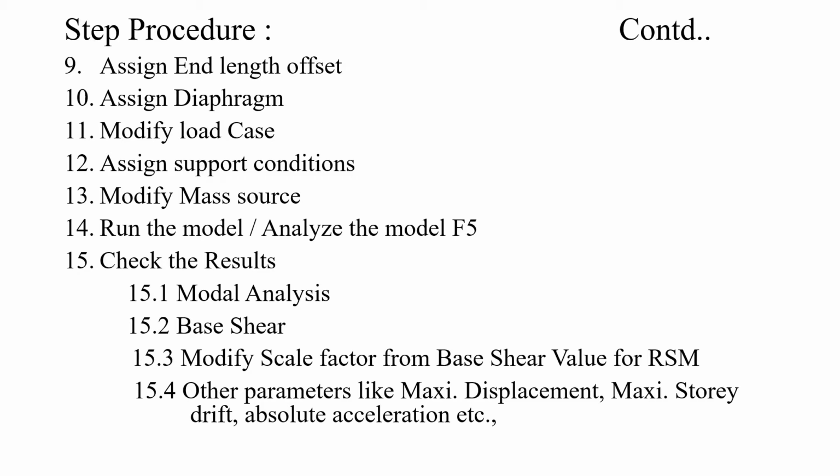And we have to assign the support condition, whether it is fixed or hinged or pinned. We have to modify the mass source. Then we can analyze the model. After analyzing the model, we can check the results.